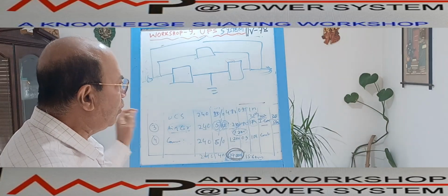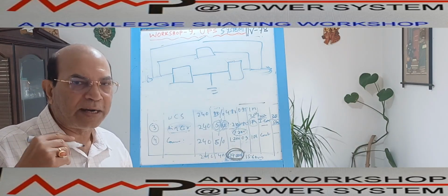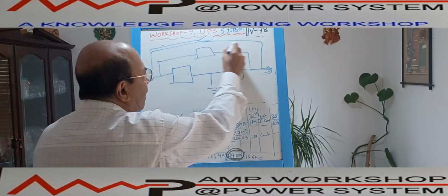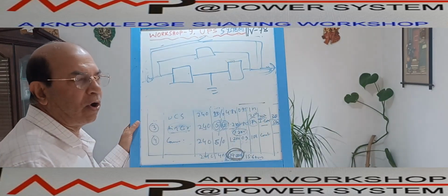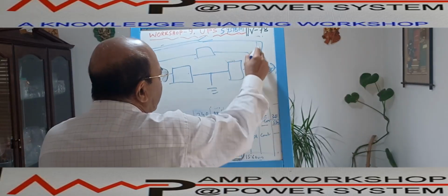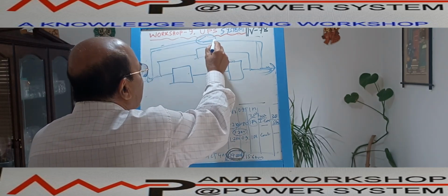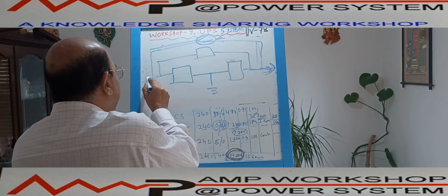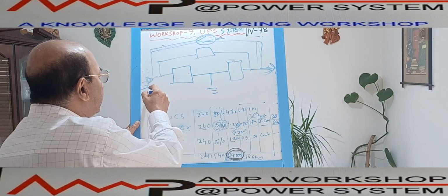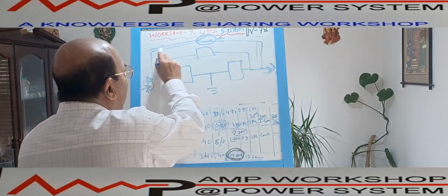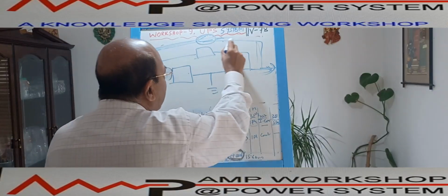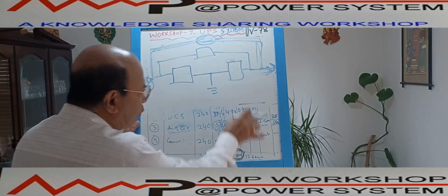So if the critical load is coming during startup only, at that time, during startup, I will switch on the maintenance bypass and I will start the motor, or I will start all the inrush devices, because at that time the power is going through the maintenance bypass, through this cable and this switch, means MCB or breakers, and this is connected to the main source, our main power supply. So we can consider that as infinite capacity, and we have sized this cable based on the inrush current, all these things.